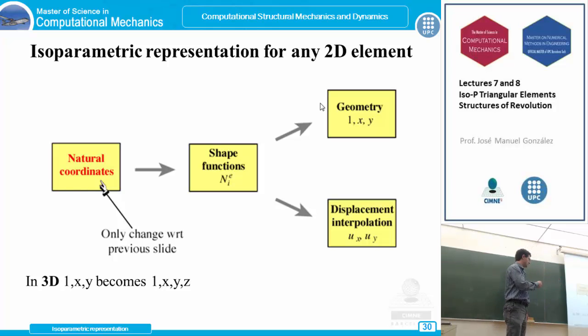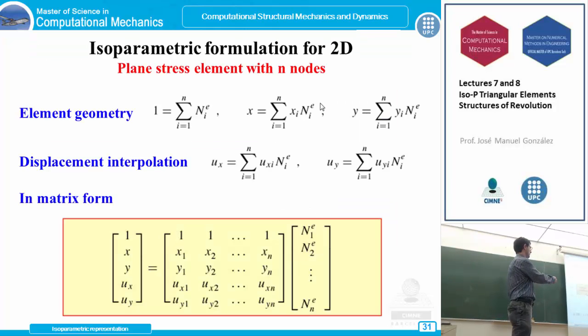Of course, as we told last day, this scheme is perfectly extendable to the 3D problem, just taking into account the z coordinate apart from the x and y coordinates in the plane problem. So this is the scheme we use for the quadrilateral elements, and we talk about how to find the shape functions using the line dot product and the steps to get to the stiffness matrix and the consistent nodal vector. And now we are going to do the same for these triangular elements, all the triangular elements, any of them, not only the linear one.